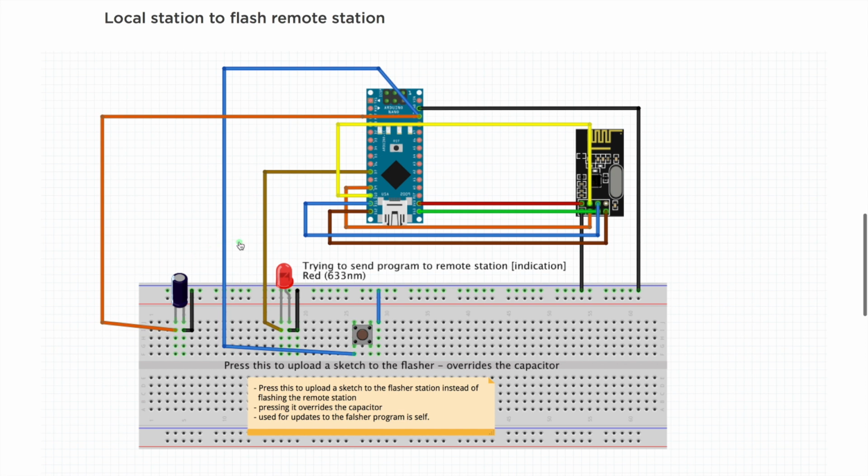But the thing is that once you connect your Arduino IDE to an Arduino and you want to flash it, the program is sending over USB here a signal that resets the board and loads it to a bootloader state, and then the computer sends via UART the packets, and the bootloader here flashes its own program.